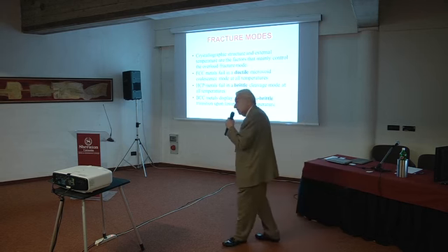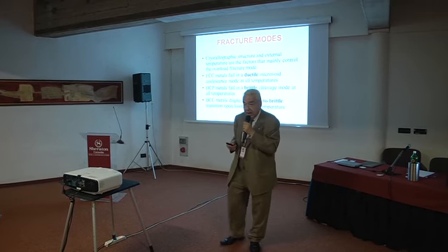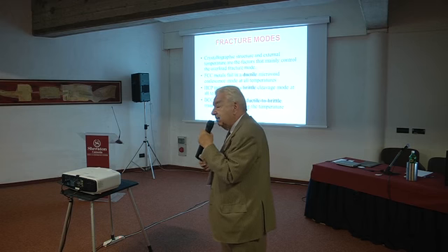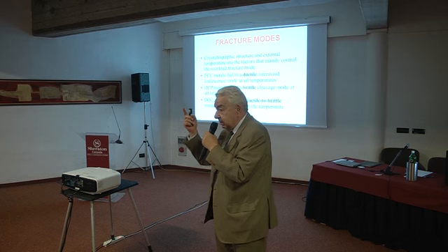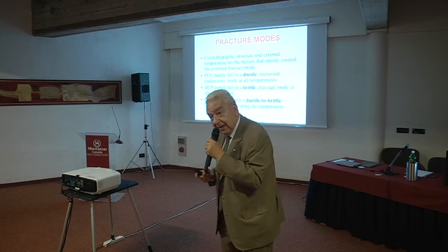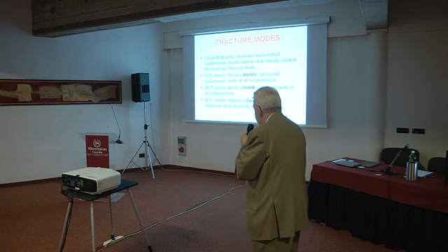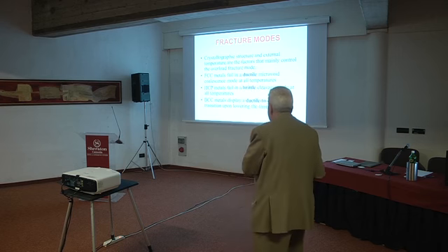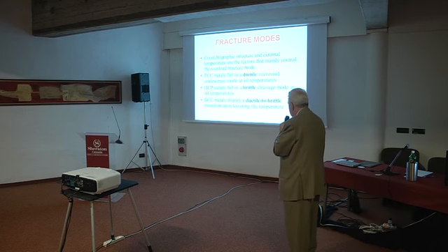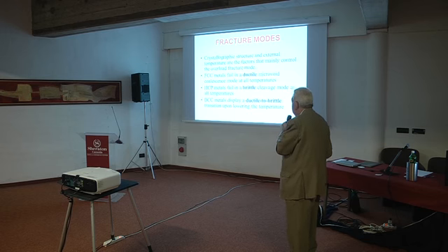FCC, face-centered cubic, is a way in which the atoms are together very compact. They are compact in all the directions. And here we will have a ductile microvoid coalescence mode at all temperatures.